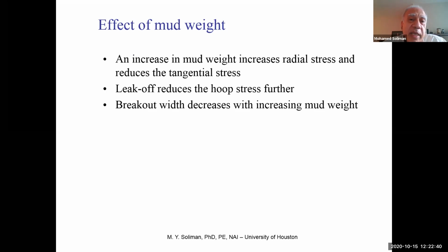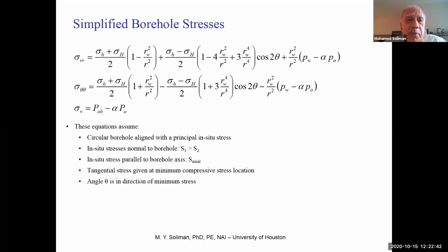So how to take care of it is you increase the weight of the mud. And here is the equation considering the pore pressure and the depletion of the formation. So here I have wellbore pressure and I have pore pressure, and obviously here you'll be considering Biot's constant.